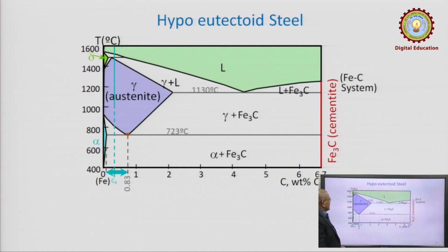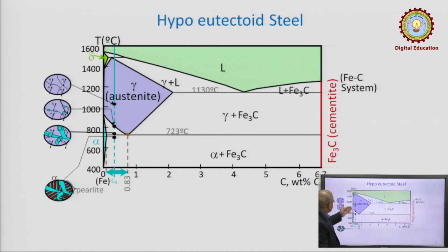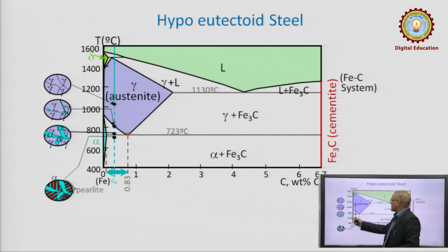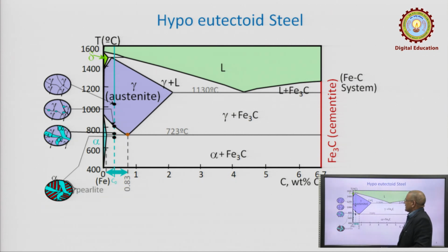These are the parts of the iron carbon equilibrium diagram. Partly you can see this process. We want to know at various points what the microstructure is. How does austenite look? You can see the austenite structure here. The austenite grains are there, and the two grains are separated by grain boundaries. In this region, as I said, the material is in the austenite state, and this is complete 100% austenite. So, you can see the complete austenite grains.